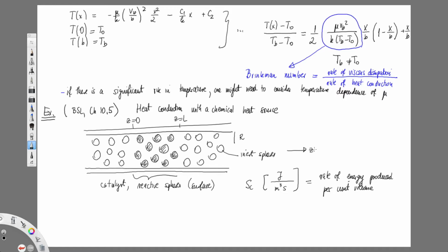But we will average, so we will assume that we have a front moving through, and that front moves at the Darcy velocity. So that's sort of a plug velocity. We will treat velocity in an averaged way, since we do not have an analytical solution. And quite frankly, even if we had it, it's a lot to deal with if you have a complex geometry.